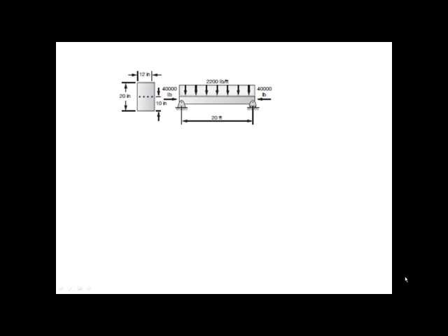You can see by the cross section the area is going to be 240 square inches. So therefore our axial stress, P over A, is 166.7 psi. It's a compressive stress, so that's going to be a negative.